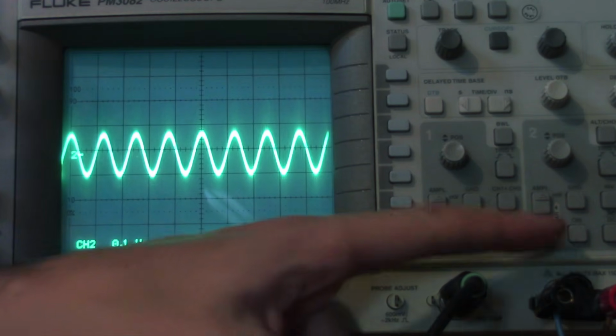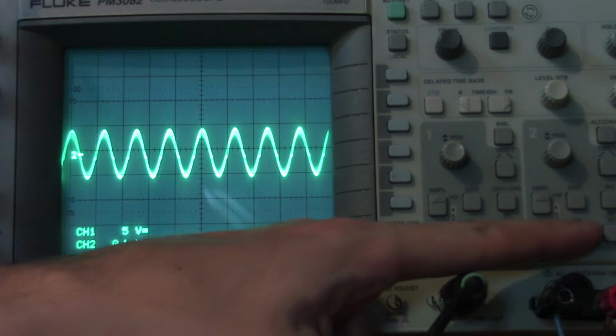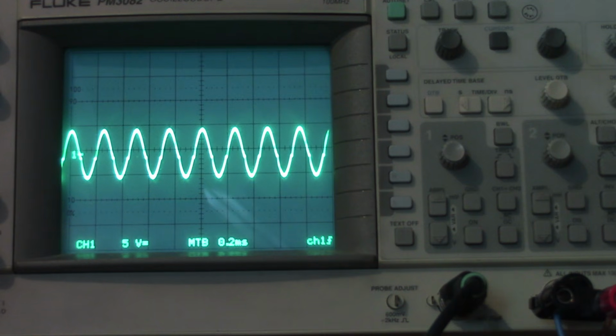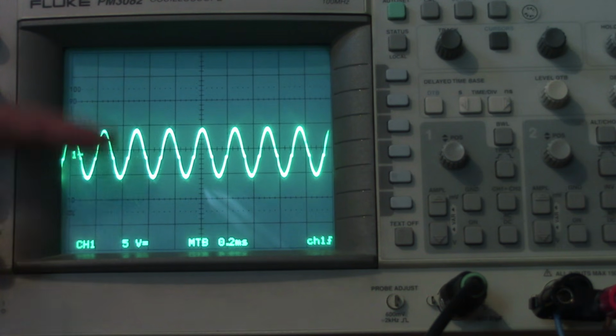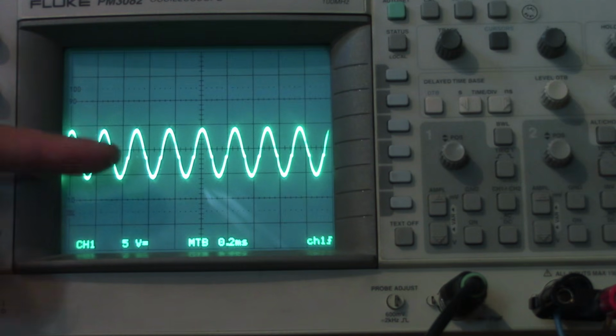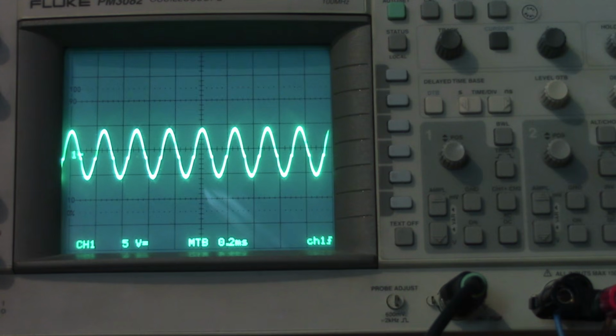Then if we switch over to the other channel for a moment, this is the output of the circuit, and you can see that signal has a much bigger amplitude, right? The scope is set to 5 volts per division, so each box on the screen is now 5 volts, which means this signal has about a 5 volt amplitude. So it's significantly larger than our input signal, which means the circuit that I've built significantly amplifies the signal as well.